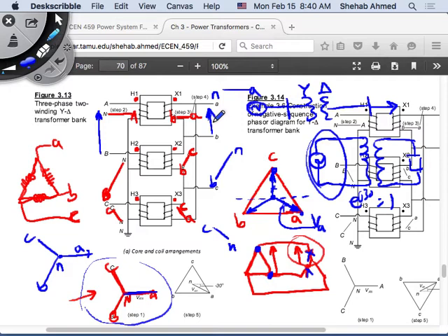What I know is that what's inside is a delta. This delta, I take it and connect it across an equivalent imaginary star. And then I look at the phase voltage across phase A on this imaginary star. That voltage is what I will put in my single phase equivalent circuit. And that's the voltage that will dictate this e to the j30. I know it's going to be 30 degrees. Okay, we know that. But where did that come from?